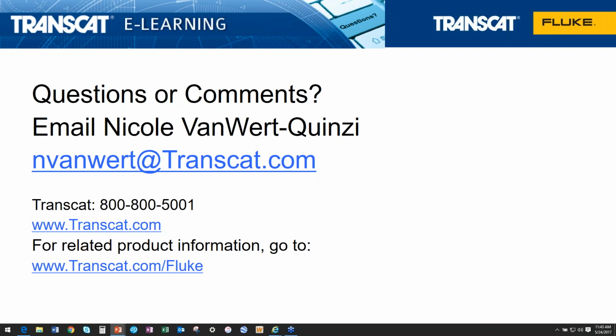Someone duplicated a question. We use a Fluke 754 and several 750 series pressure modules. I found that sometimes the 1 and the 5 PSI modules are quite difficult to zero. I press the zero button and the module will give a negative 0.3 inches of water reading. Sometimes it takes 8 or 10 attempts to get the module to remain at zero. Does that sound like something you've heard?